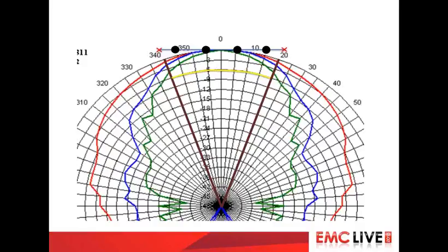What we're looking at there is, you see the red radiation pattern and its beamwidth, its slope shape, and then you see the blue, and then you see the green. You see they get narrower and narrower and narrower. What that yellow line means is a keep out area. Below that yellow line and within the segment marked by the two brown lines is a keep out area. Your beam is not allowed to fall within that area. Because by definition, if it's 0, you're at your minimum, you're at 18 volts a meter. You must have exceeded 36 volts a meter for the beam, which is going to end up where those red crosses are. It cannot be more than 6 dB away, because it would then be in excess of 36 volts.